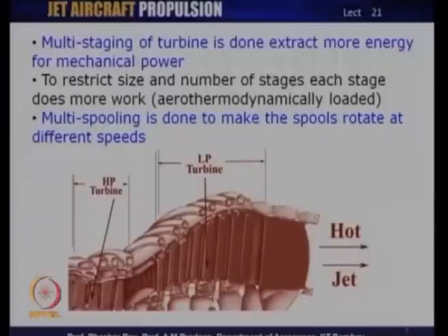And one of the reasons is, in aircraft operation, it has to work under various operating conditions during its flight, during takeoff, during climb, during cruise. All these conditions require different kinds of atmospheric conditions, different kinds of working conditions in front of the turbine, and as a result the turbines may be required to operate under different operating speeds or rotating speeds.